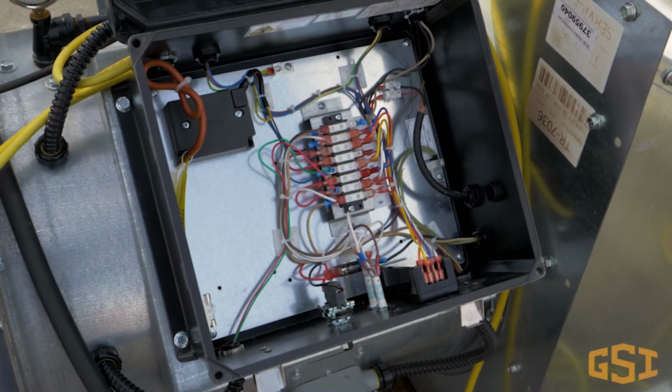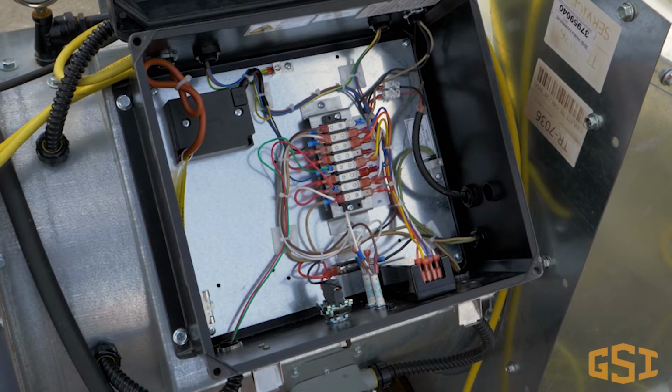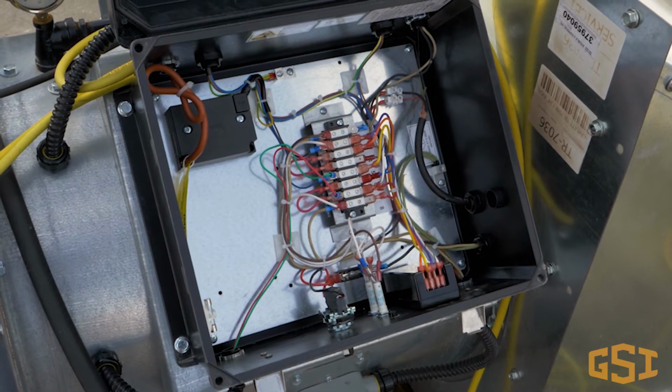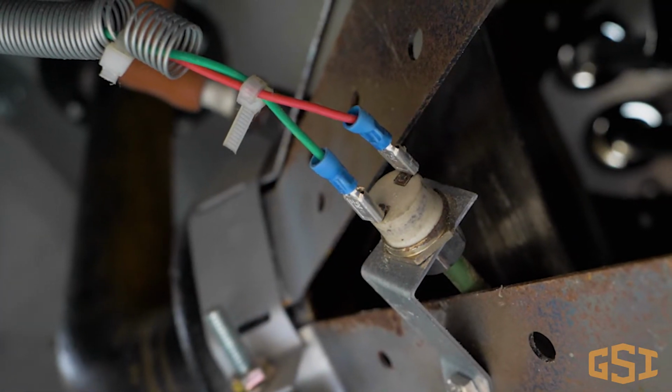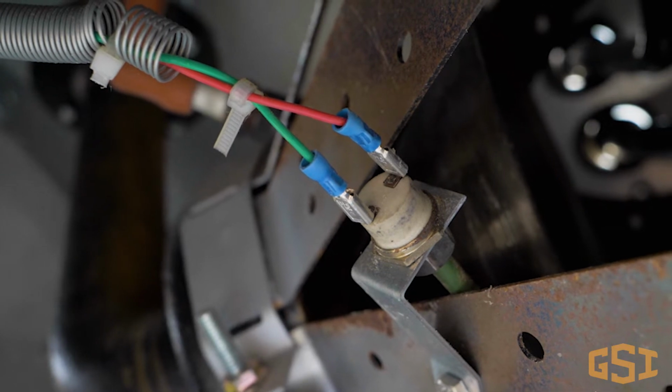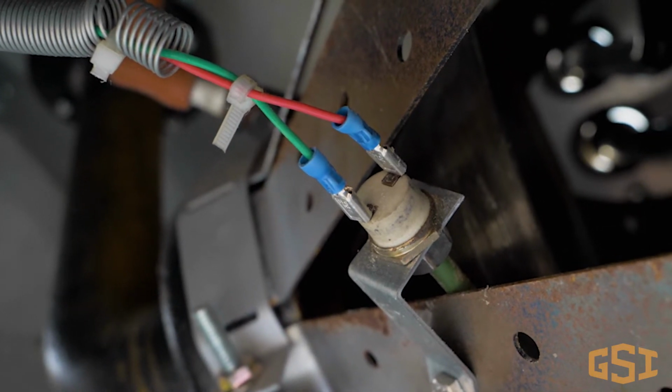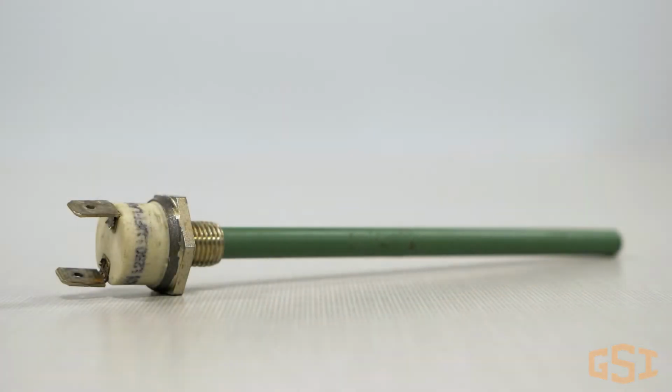Before we begin troubleshooting, let's take a closer look at the control circuit and flame switch used on standard heaters. Notice that I use the term flame switch and not flame probe. Standard heaters use a flame switch for flame sensing. Inside the flame switch's heat-treated housing is a set of normally closed contacts that open when the housing temperature reaches a temperature of 250 degrees Fahrenheit.